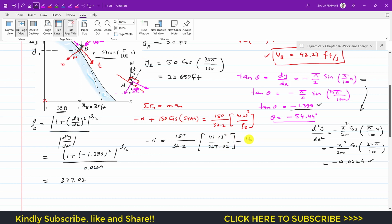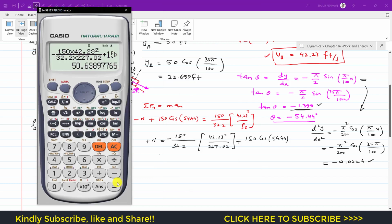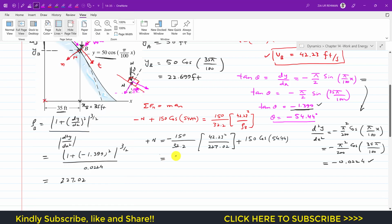So this is minus 150 cos of 54.44. Now if I multiply both sides of the equation by a negative sign, this will become negative and this will become positive. So from this equation we get N equals 50.64 pounds. This is that N value at point B.